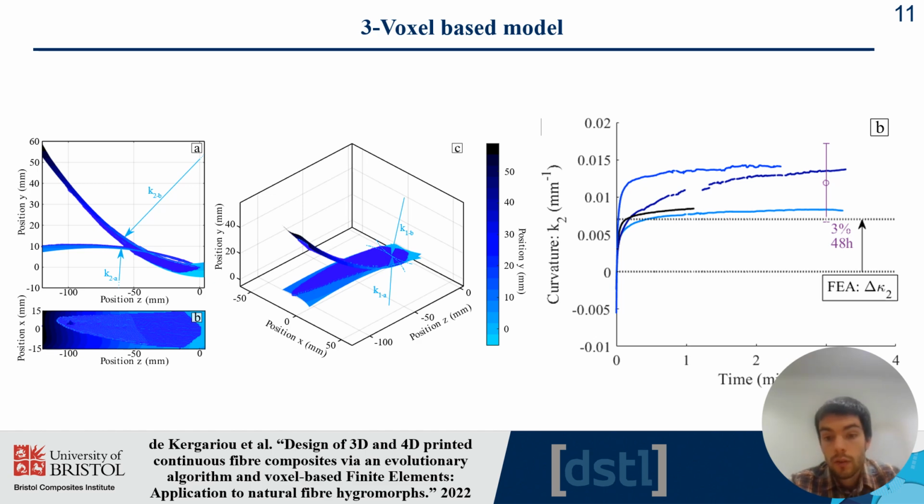different things that we discuss extensively in the paper. If you're interested, I'm going to talk about two. The first one is basically the humidity. When you measure a specimen inside a glass box at 98% relative humidity, there are drops of water that go on the specimen and also on the box, and this perturbs the measurements slightly. The smaller the distance, the more sensitive it is to this perturbation, and therefore the small distances that we have been measuring had a lot of variability in the results.